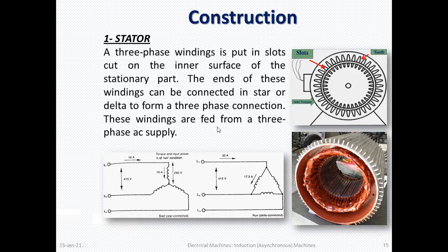So this is the stator point of view. Here a stator cut view is shown. Here slots are there, and windings are placed in these slots. And when the three-phase supply is given, what will happen? A rotating magnetic field is produced, and if a rotor is placed here, then this rotating magnetic field will induce EMF in the rotor, and the tendency of the rotor